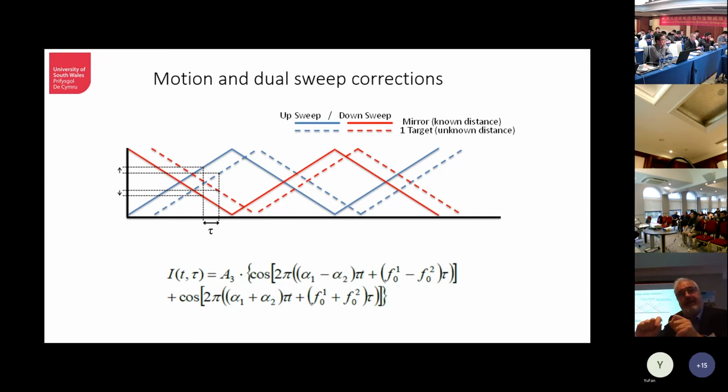Because you've got an opposite direction of chirp, it allows you to cancel out the vibration in one component. The vibration comes through as a very low frequency component, almost close to DC, which can be filtered out. Your beat frequency is in gigahertz, and you separate out the vibration on its own close to DC, which you can filter out because of this nonlinear process and multiplication. Then you've got the signal itself on its own. So you can take this out in real time, you do the measurements, and the vibrations are completely eliminated.